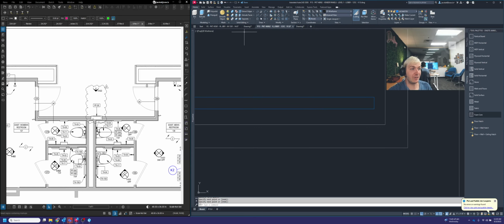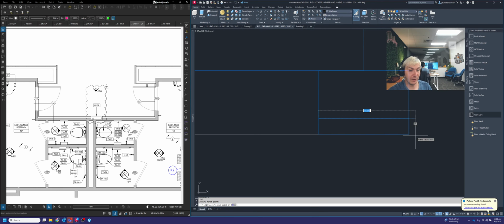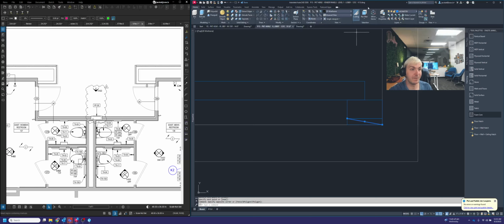Those reveals will consist of a 3/4 inch block by 1.5 inches wide, so 0.75 thick, 1.5 wide. I'm going to stack that right behind the panel and butt it to the drywall. So there's my line of wall, there's my panel, the back of my panel there. And then between that full depth reveal and the actual wall and the back wall, we need to throw in some shim right there. So we'll add in a 1/4 inch of shim, a 3/4 inch full depth reveal, and then our 3/4 inch panel right there.